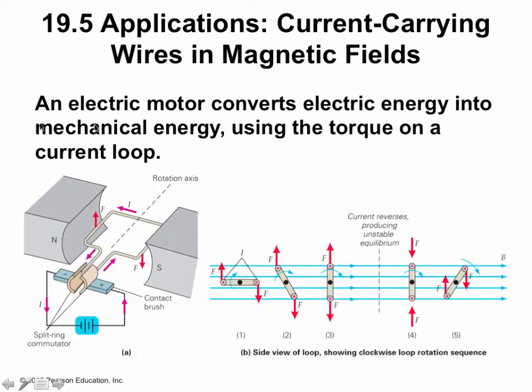So then the electric motor kind of works on the same principle, except if you have a brush motor, we apply a current through some sort of power supply, and you have the positive contact brush here and a negative contact brush here. As this rotates, the current always enters in this way and flows out this way, which has a force based on the right-hand rule going up here and going down here. As it rotates, then the currents will continue that electrical path.